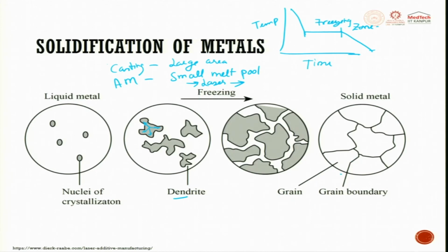Grain boundary is a place where a lot of energy is available. So, you can try to do that at ambient, or you can try to reheat. First round you try to melt and next round you try to heat, or during heat treatment after the process is done through additive manufacturing, you can slightly play with the grain size, grain orientation and the grain boundaries. You can do it. This is the basic understanding you should have, because even in the melt pool, whatever we are talking about, all these phenomena happen.